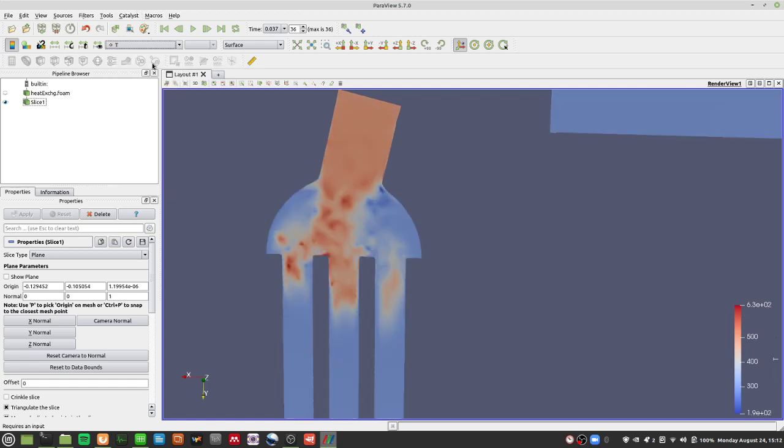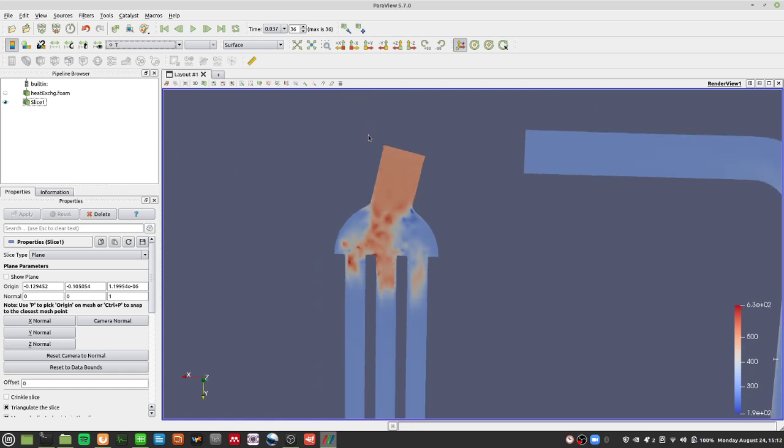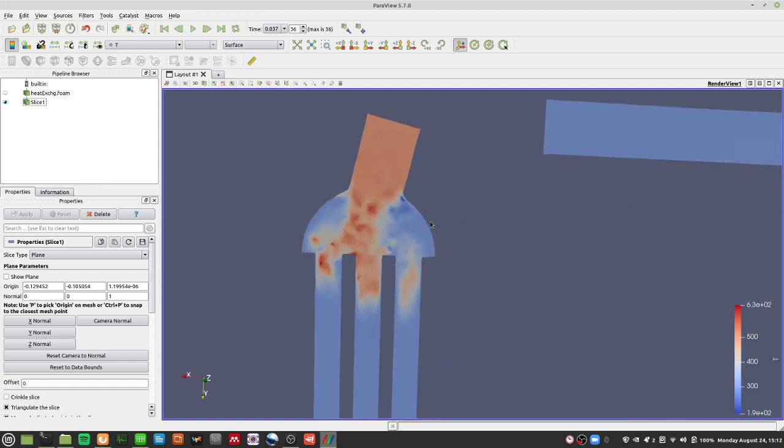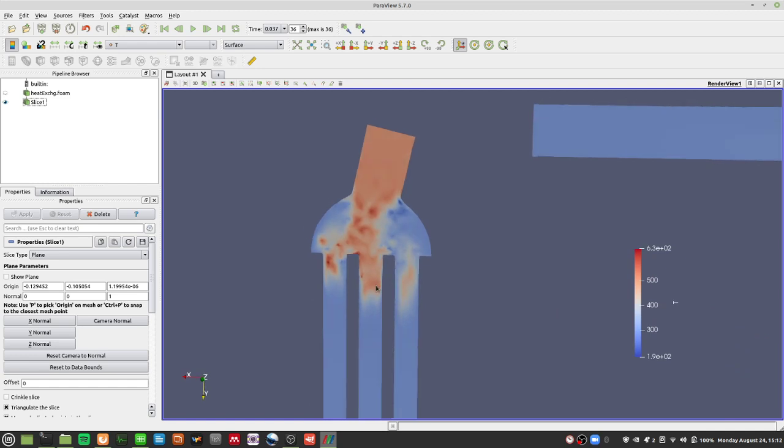And if you take a look, of course, at the temperature field, remember the temperature is supposed to be 500 Kelvin, so to speak. And then now that the fluid is going in, suddenly there are parts of the fluid that become 600 Kelvin. Could it be because of a slowdown, or maybe it's solver instability? Well, these are the things we also have to take a closer look at.